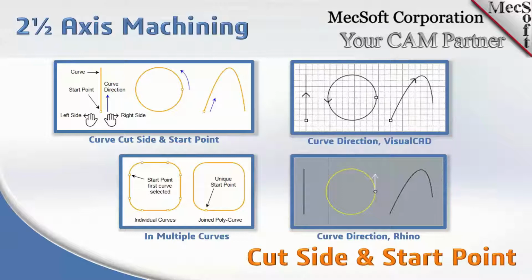If you look down below that, you see using multiple curves. On the left, we have 1, 2, 3, 4, 5, 6, 7, 8 curves that are closed, but they're not merged into one single curve. So you see start points at each of the curves. We highly recommend that if you're going to machine more than one curve, you merge them into a single curve.